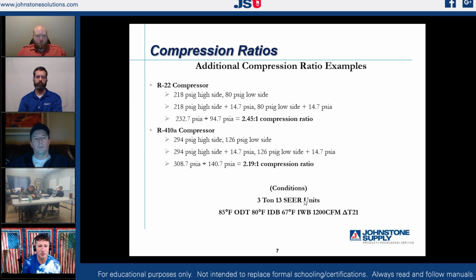So it just changes our perspective on how compressors are designed and why we're changing compressors and working with refrigerants. As we were talking about over the last two classes, we have to find refrigerants that are going to meet in the middle, to find that happy place between cost of production, cost of use, cost of manufacturing the equipment, and being environmentally friendly. There's a lot of factors that come into play, and one of them is the efficiency of a refrigerant. We could have a refrigerant that is inexpensive to manufacture, but it might not perform very well. And if it doesn't perform very well, it's going to end up affecting our compression ratio, which is going to end up affecting the amount of current on our motor.